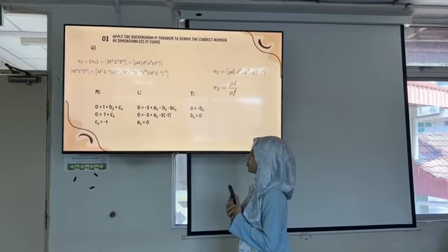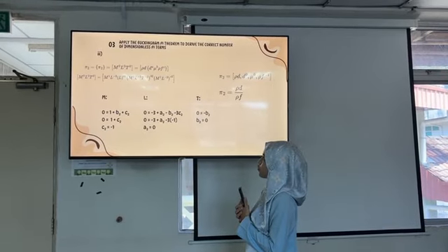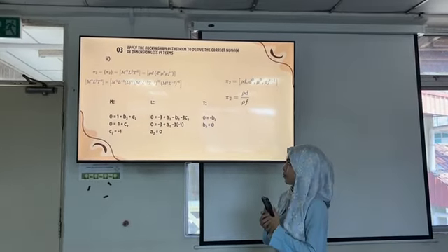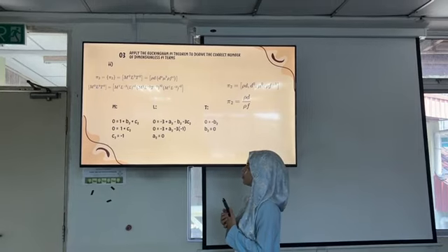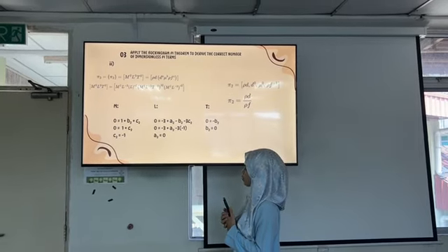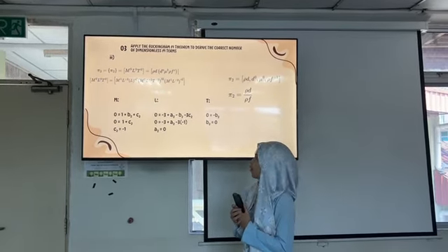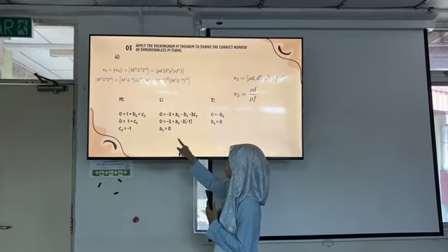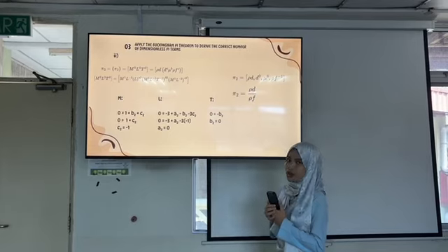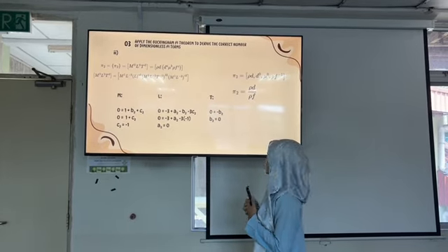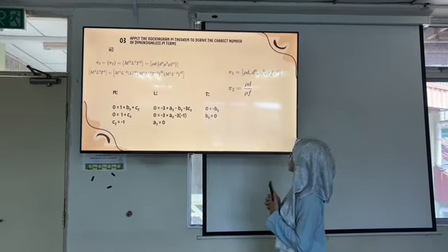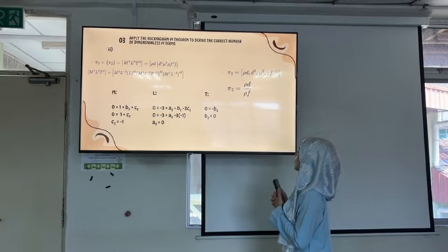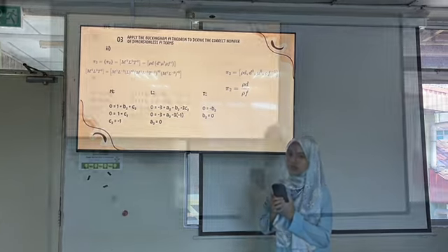Next we solve for pi 2. We choose rho d as the non-repeating parameter, substitute the dimension variables into the equation, and we solve for the m, l, t values. So we got c2 equal to -1, a2 equal to 0, and b2 equal to 0. Substitute the values into the original equation, and we simplify. We got pi 2 equal to rho d over rho f.